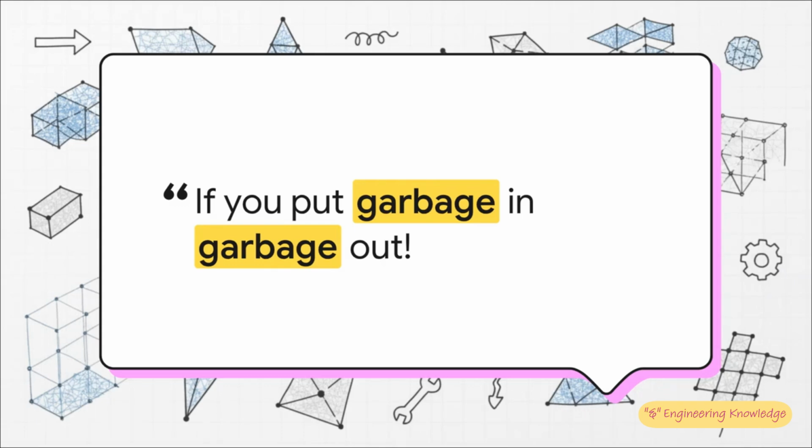But before we get too swept away, let's establish the golden rule here. Garbage in, garbage out. It is so tempting, isn't it? You look at this beautifully rendered, brightly colored 3D model on your screen, and you just want to believe it represents absolute reality. But here's the catch. A colorful stress contour means absolutely nothing if the underlying mathematical mesh is flawed. If your foundation is off, those pretty pictures are, well, just pretty pictures. They don't represent reality at all.